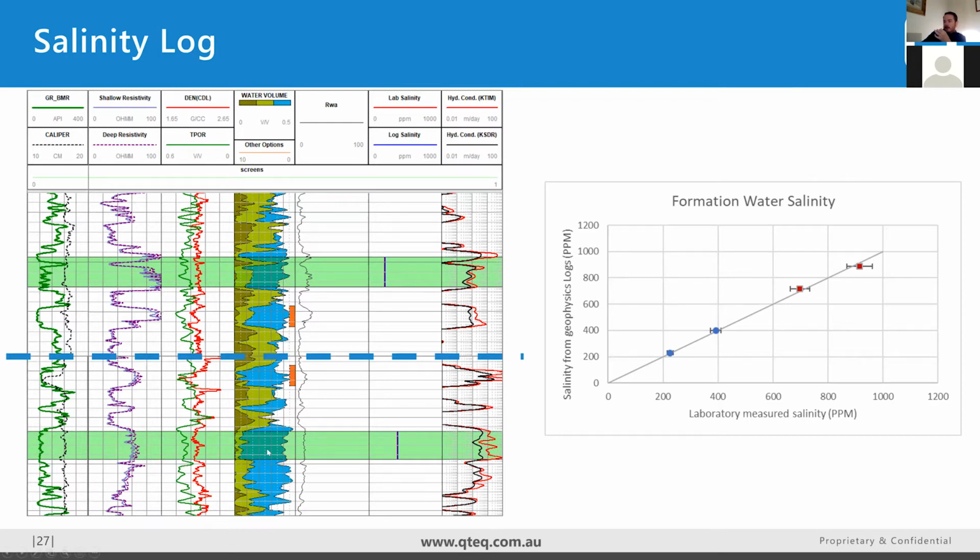So if you're looking at an aquifer for agriculture or feeding livestock, it has different requirements than for humans. So you might target different aquifers for your different end needs. It also helps you to determine where you want to set your screens. If you're trying to optimize your bore, you'll only select screens that will target the aquifer that you're most interested in.